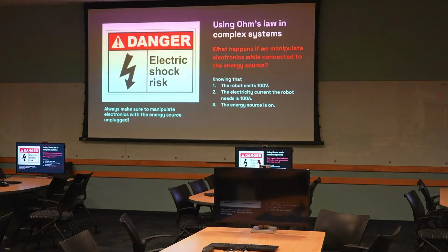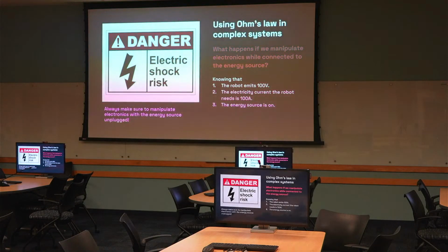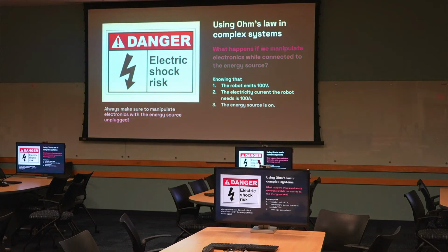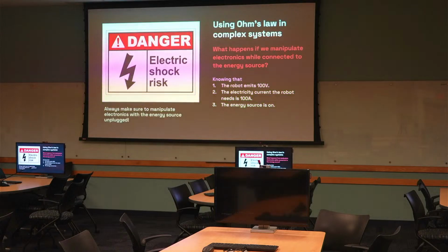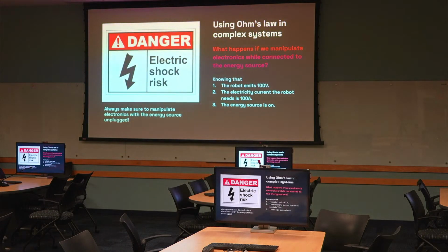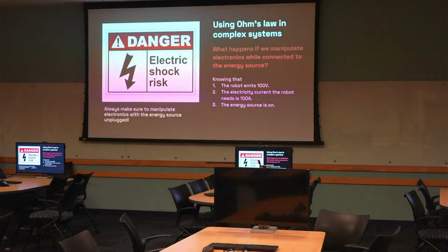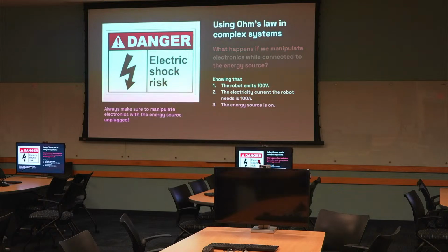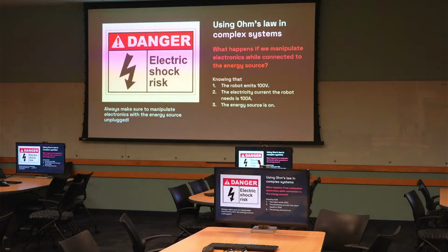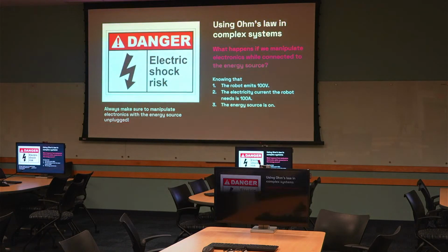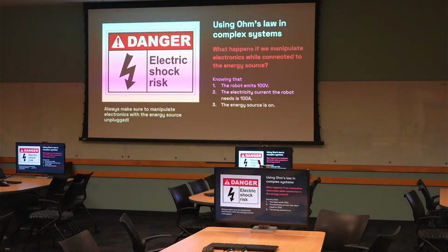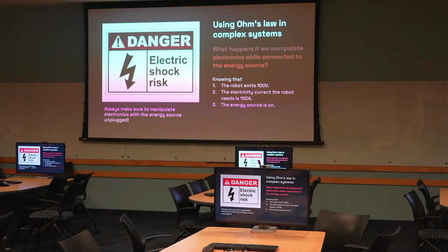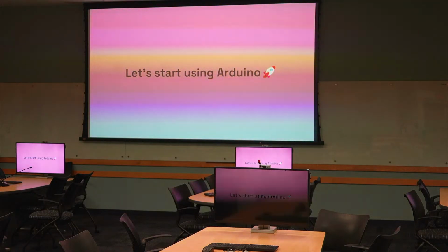So it's always good practice, if you start doing it now, although nothing is going to happen, that you unplug the Arduino, do your stuff, and then when you test the code again, you plug it in again. I know it might sound tedious, but trust me, it's for your safety. Because you might get into trouble in the future if you delve into more energy consuming components. That's very, very important. So let's start using our Arduino.